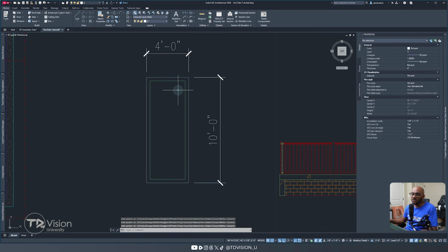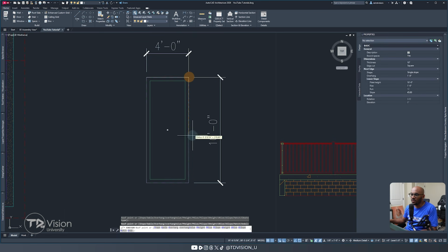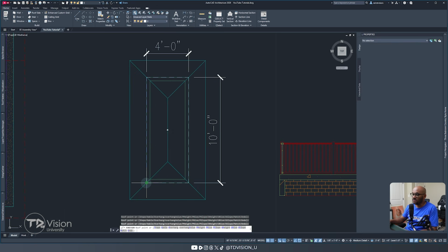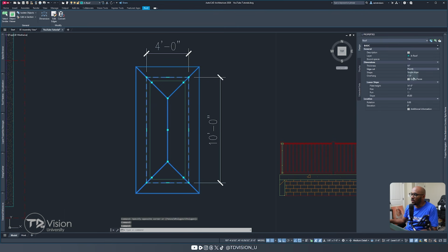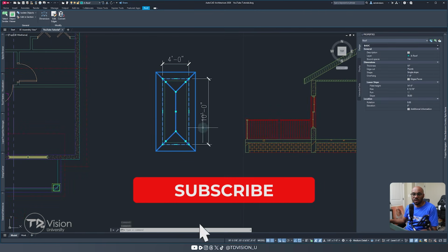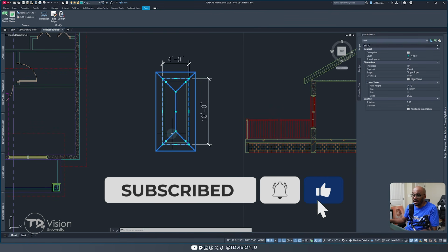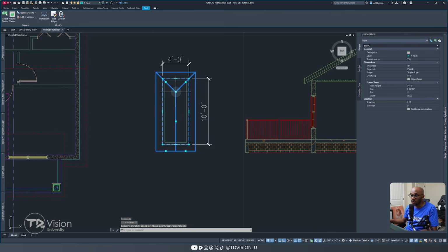Okay. Next, I'm going to add the roof. So I'll go to my roof tool here and I'll draw a roof around the edge of this. Enter. I'll also make sure that the roof is sitting on top of the wall, so we need to adjust the plate height. The wall is 14 feet tall. We need to make this 14 feet for the plate height as well. And we're going to adjust a few other things here. We want the edge cut to be plumb. We also want the slope of this roof to be 30 degrees. And lastly, I'm going to convert this to a gable dormer. So I need to grab these points and pull them out to turn it into a dormer.